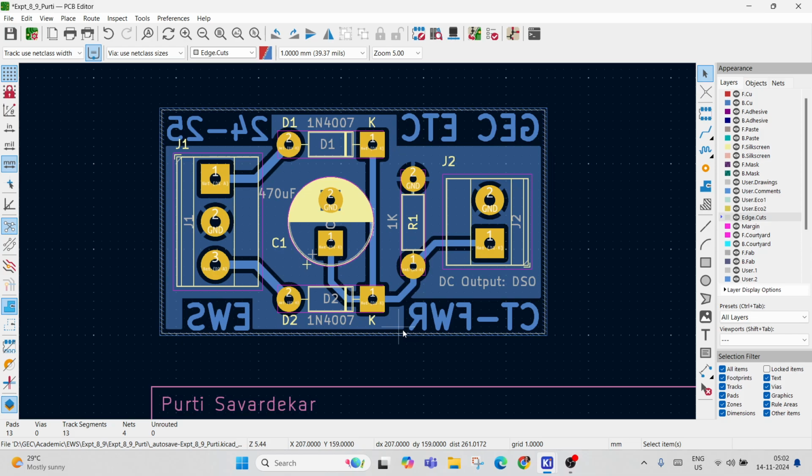We are not going to be performing milling. Milling, which is the removal of copper, is going to be happening using etching. So etching is another experiment, because of which, using the machine, we are only going to be performing edge cutting and the drilling. And these two operations are to be studied by you, not to be performed.